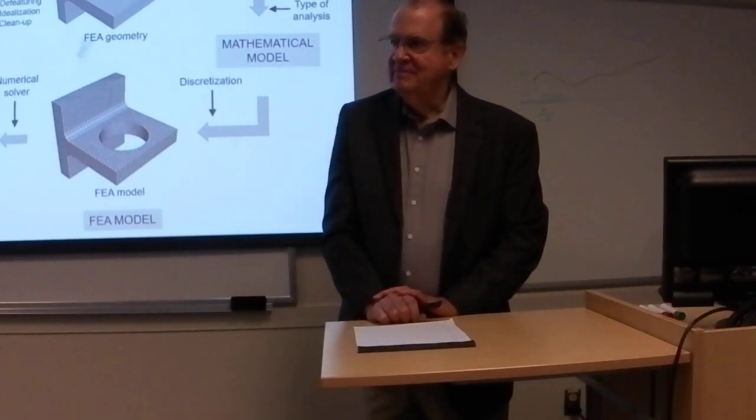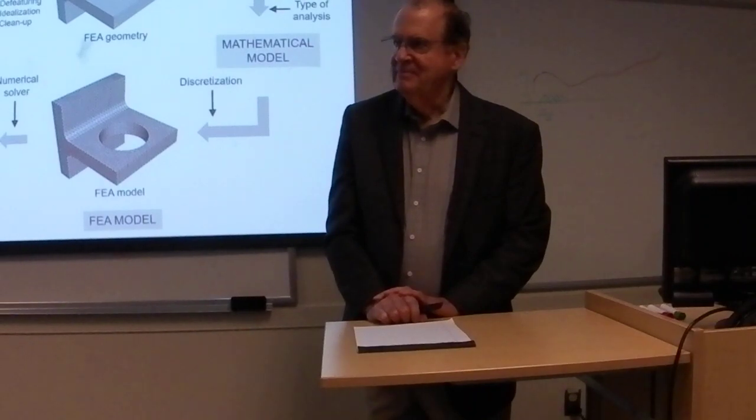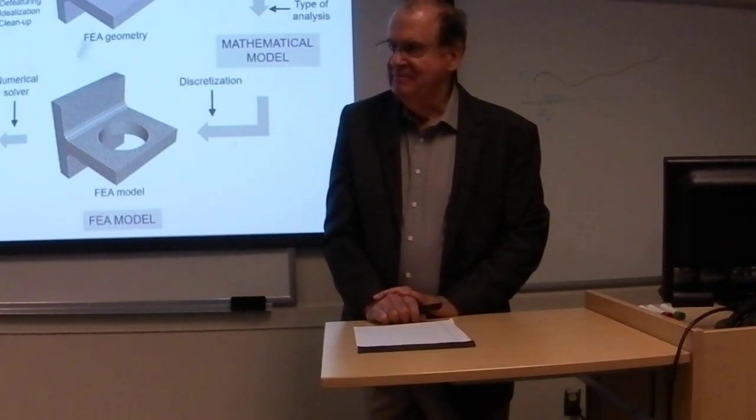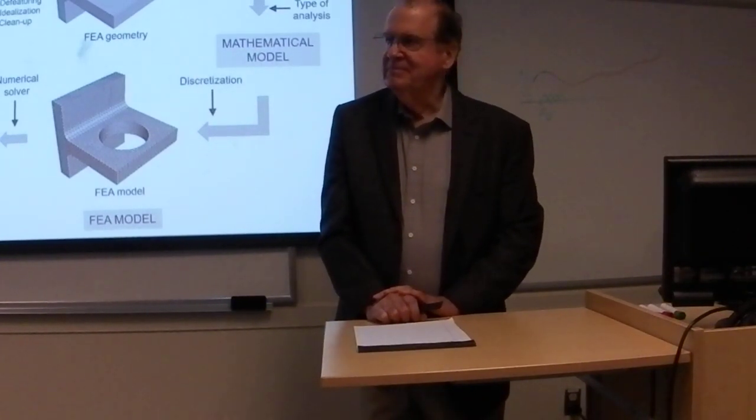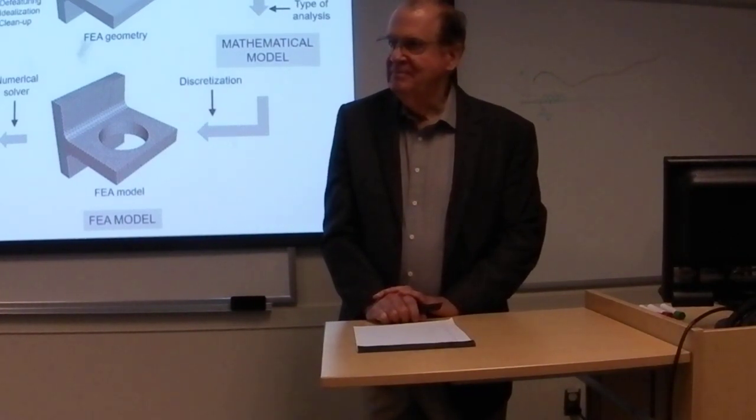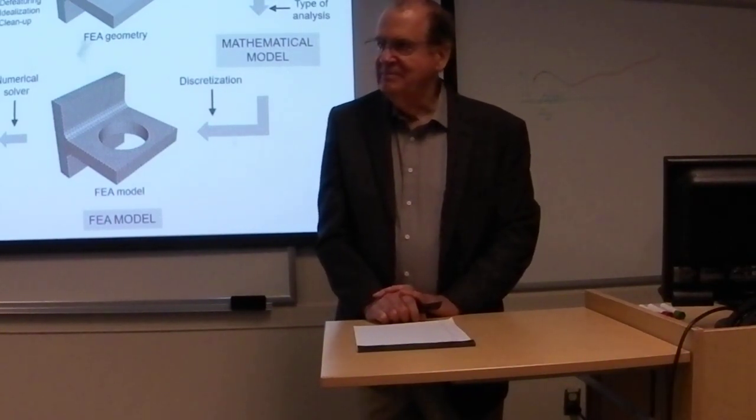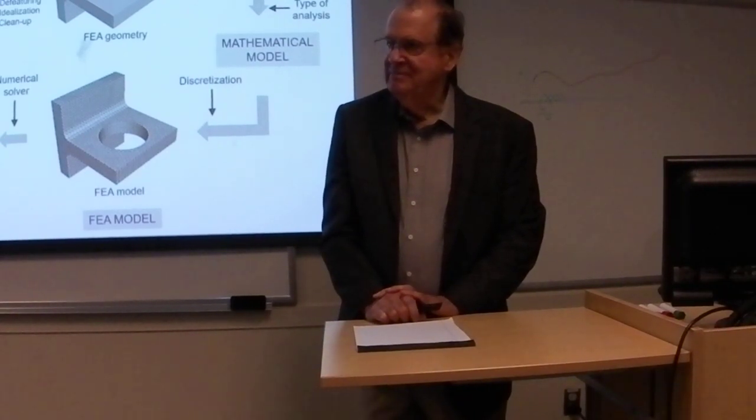So I will say, the purpose of this particular slide was to demonstrate how when you're going through the general steps of the FEA process, you start to acquire uncertainty. And so a point needs to be made about how when you move from the CAD model that's fully featured and fully detailed, and then you import it into Abaqus, what you'll find out is it tries to partition all the surfaces, and it's going to come up with a lot of errors.